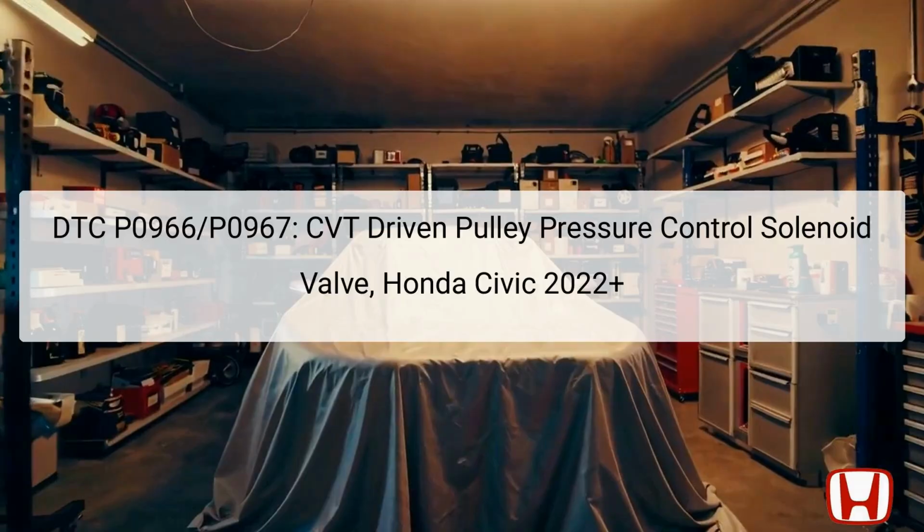The purpose of this presentation is to provide a comprehensive troubleshooting guide for DTC P0966 and P0967 in the Honda Civic model from 2022 onward. DTC P0966 indicates an abnormality in the CVT-driven pulley pressure control solenoid valve circuit due to low current detection, while DTC P0967 signifies an overcurrent condition.